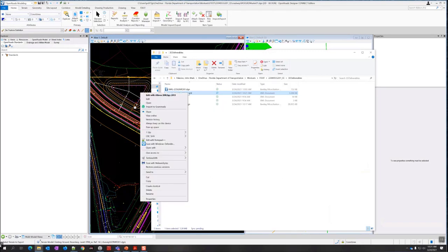You can just double click, or open in your favorite editor. If you have Notepad++, you can do this, edit with Notepad++. So that opened it up, and it does say LandXML at the top, so that's your main check. This is a much larger file because it has all the points, all the triangles. Over here it says surfaces. And because I have Notepad++, I can shrink this down. All I have is surfaces in there. So that file is good to go.